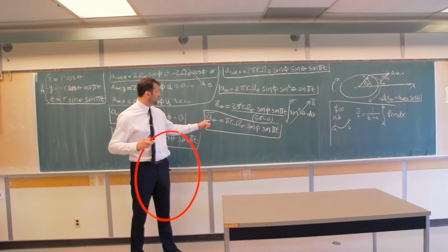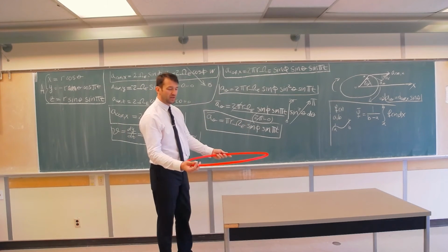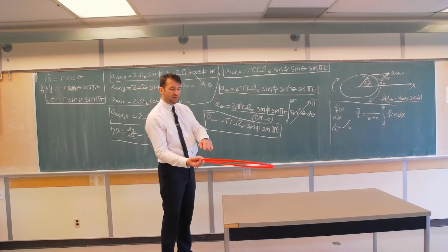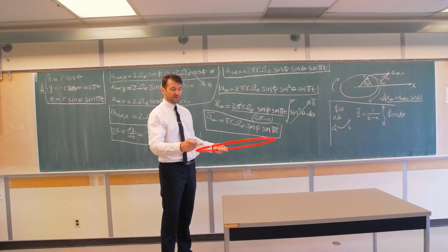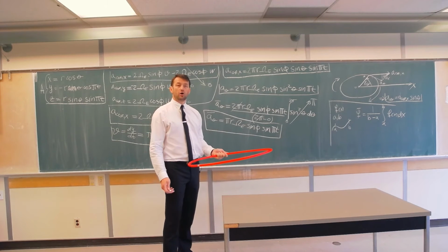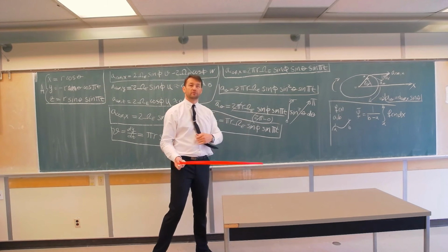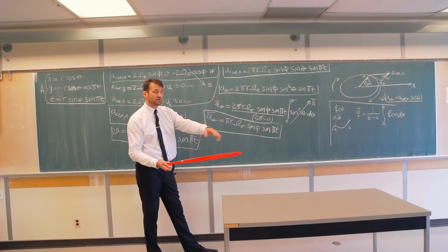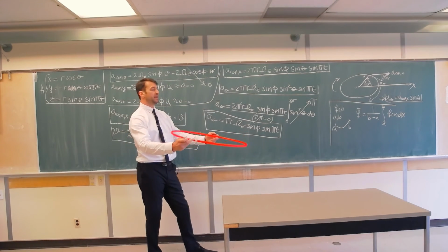What did we do here? Well, what is this? This is azimuthal acceleration caused by the Coriolis force for this point A. But we will have different values for different points, so we average around the loop. Averaging is given by that function over there, which means that this result is the average acceleration of water in this loop as we are